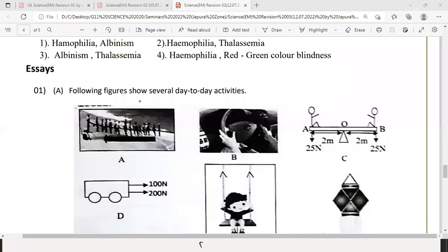But here it is not a couple of forces, because both the forces act in the same direction. Then the resultant will be what? It's 0, right? Left side 50 and right hand side 50, then it will be 0. So you have to be careful whether they are a couple of forces or whether they are in the same direction.